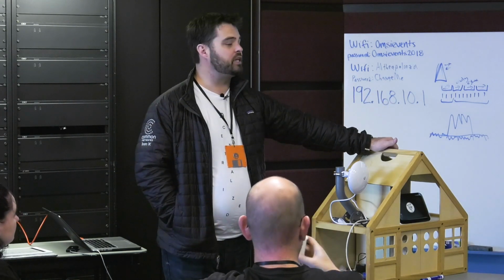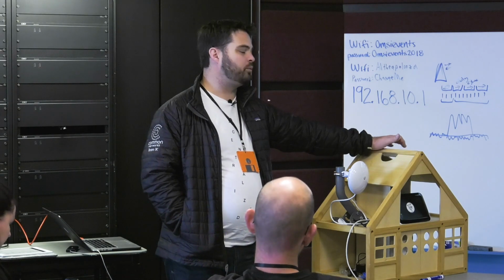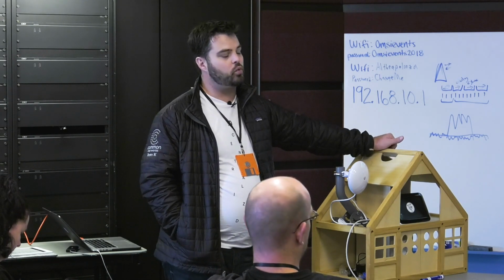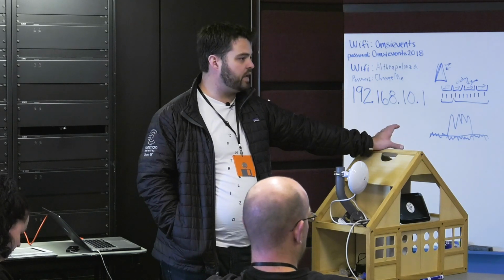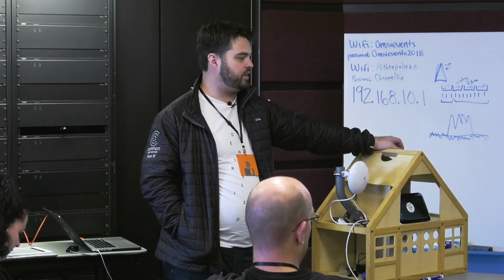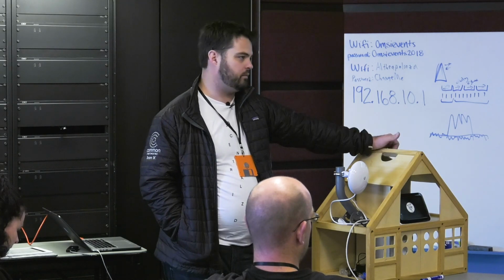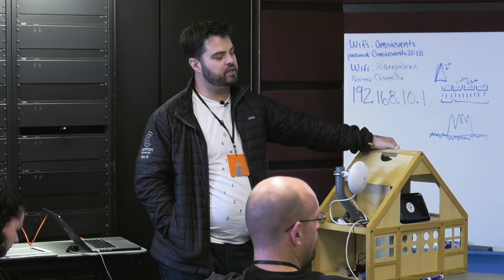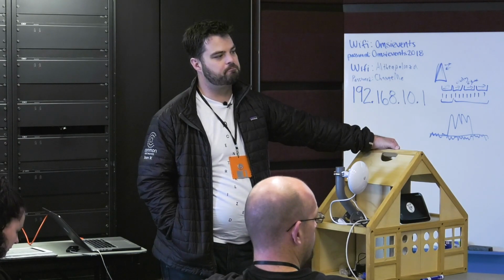The answer is typically no, because cell phone providers are using very different frequencies than we are. If there is another wireless provider, like a WISP on there, then you might run into concerns about that, and you'd have to work with them or figure out a way to not do that. But if it's only cell phone companies, you probably won't have any interference.